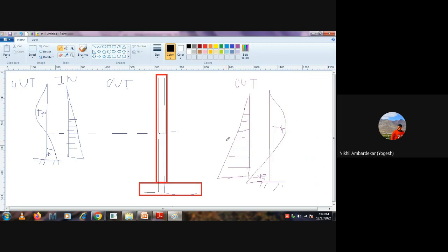Okay, this is just for the vertical reinforcement. So in practice we cannot have the upper piece separate and the lower piece separate, breaking it and placing it here. So practically what we do is provide one bar throughout, or maybe we can provide some lap also if the height is more. Correct?